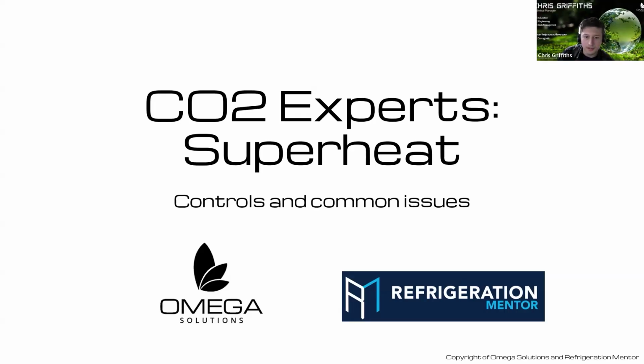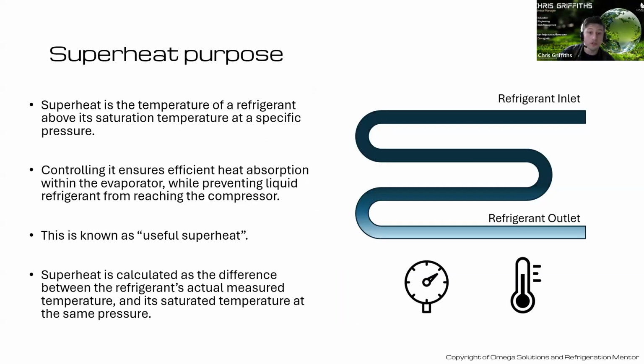So hopefully most people are familiar with what superheat is in a refrigeration system, but let's just clarify it for everyone in case they need a refresher. When we talk about superheat, we're talking about the temperature of a refrigerant when it's raised above its saturation temperature at a specific pressure. This will vary per refrigerant type and also for each application.